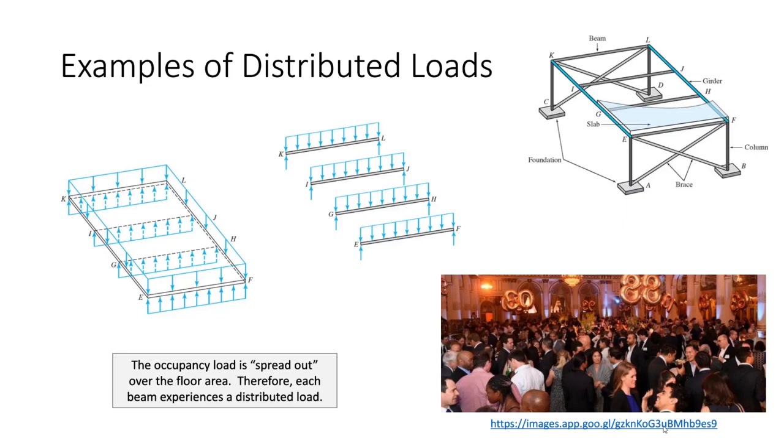Instead, what we do is we look at what this structure is being utilized for, and we develop a pressure load to apply to that system. More often than not, we don't need to come up with those loads ourselves. There are guides and references that we can use. For example, one of the most commonly referenced documents in engineering, period, is ASCE 7. ASCE 7 is a document which is like yay thick, and all it does is detail minimum design loads for buildings and other structures. It will detail what snow load you should be using in Huntington, West Virginia, or how much wind you should be designing a building for depending upon how tall it is, or its exposure category and all that stuff.